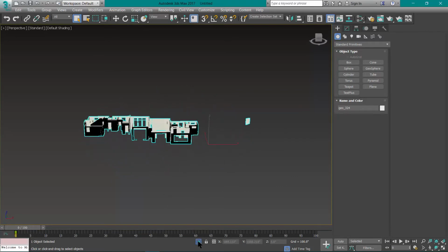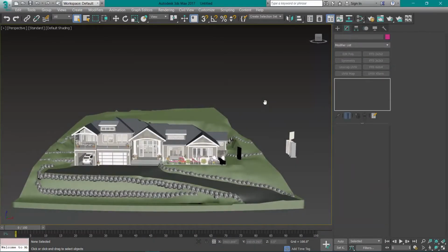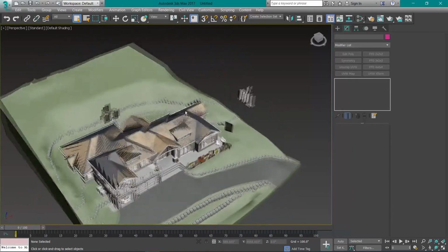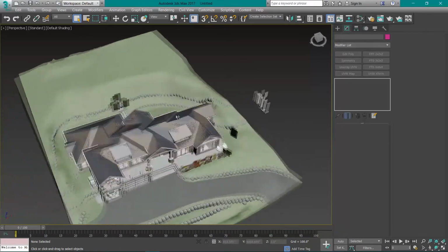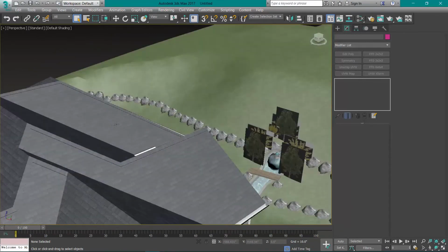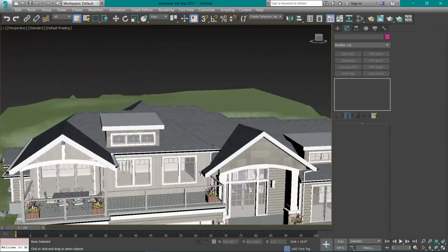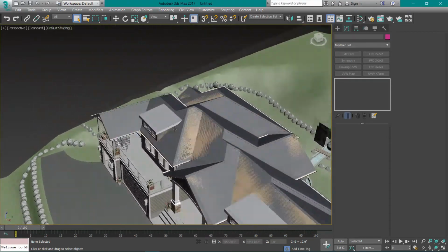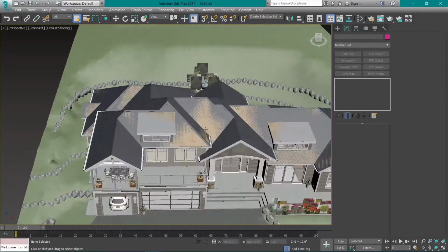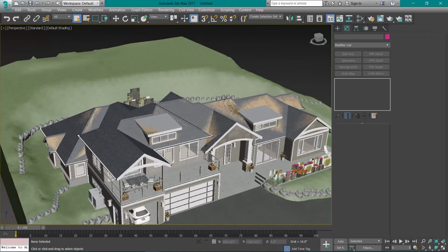So not too shabby. Another thing that can go wrong is what we call Z-fighting, and that's just like a flicker between geometric shapes. See how the subroof and the roof are fighting for viewing space? If I zoom in here, it's not so bad because the computer can handle it better at closer ranges. When I pull back, it gets pretty gnarly. Depending on what software you're importing into, some things handle this better than others.